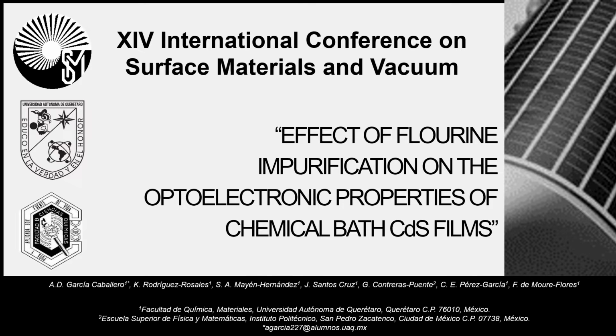CdS thin films have been used as window and n-type semiconductor in CdS/CdTe. CdS films prepared by CBD usually present high resistivity. In order to overcome this, CdS films have been doped with several elements. In this work, semiconductor films of CdS impurified with fluoride were produced using the chemical bath technique.